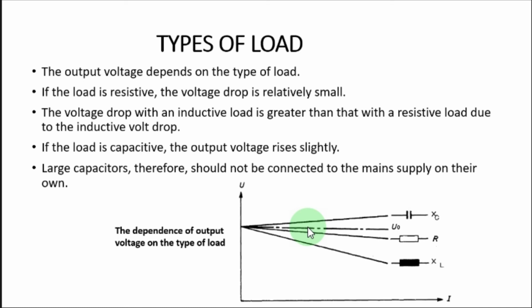That means quality high means it can maintain the output voltage independent from the load it is taking. So it is like V no load voltage minus V load voltage divided by V load voltage is called the voltage regulation.